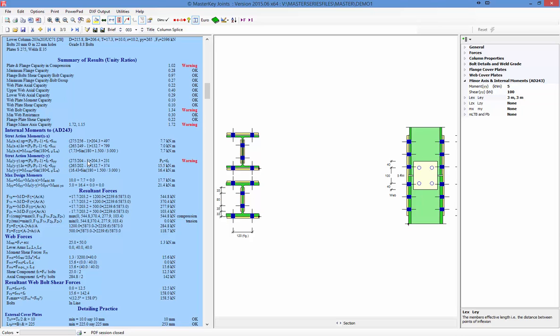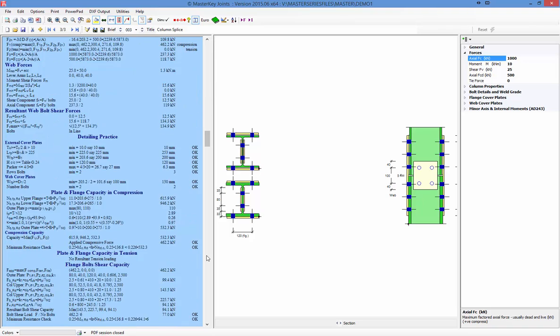So my imaginary joint, to have minor axis loads, is probably having too high an axial load. So pull that down to 1000, and that's now happy. We're not overstressing locally in the material, but what we do have is the web and the minor axis flange capacity to sort out. So let's look at the web first.